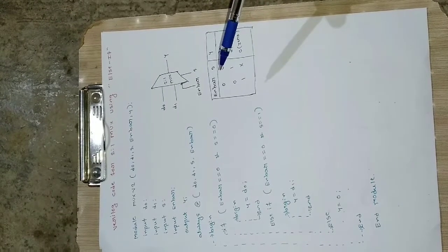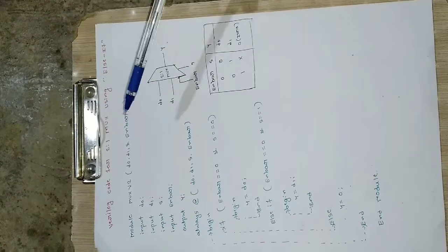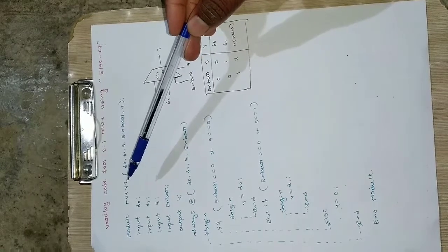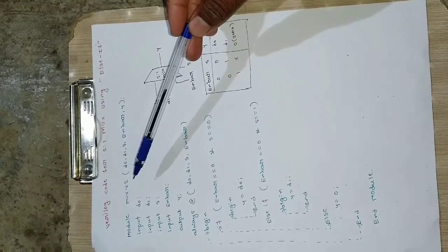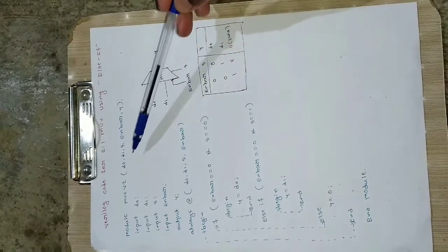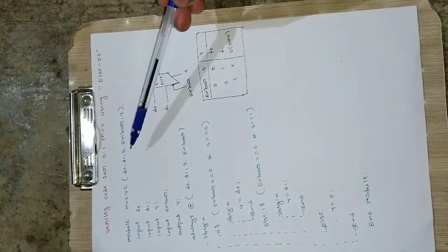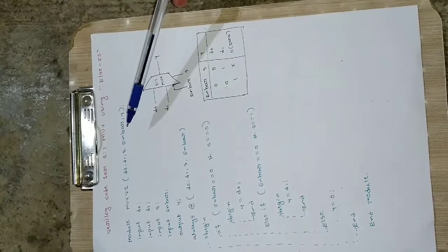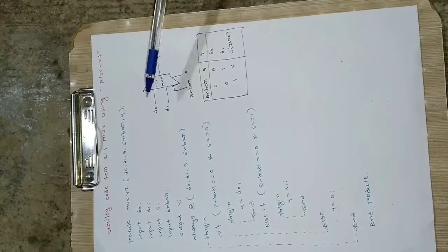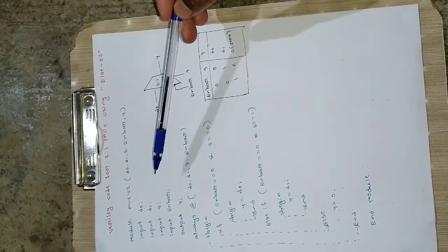Okay, so how can I write the code for this one, let us see. So that is the Verilog code we are writing. So module MUX_v2, this is the user defined name which I can give. I have given it as MUX, V for Verilog, 2 for 2:1 MUX. Then we have to write the input and output parameters in the bracket here. So D0, D1, S are the inputs and enable bar is an input. Y is the output here. So whatever input output pins we are using in the design, we should mention here. Then specify what are the inputs and what are the outputs.